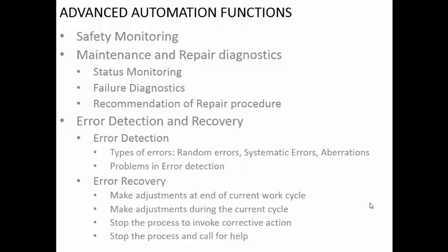So it will not happen that you are machining a component and the bearings fail, and the component is damaged. That is the advantage of status monitoring. You will know what exactly is happening inside the machine and whether there are any signals indicating a future failure that can happen. The next one is failure diagnostics.